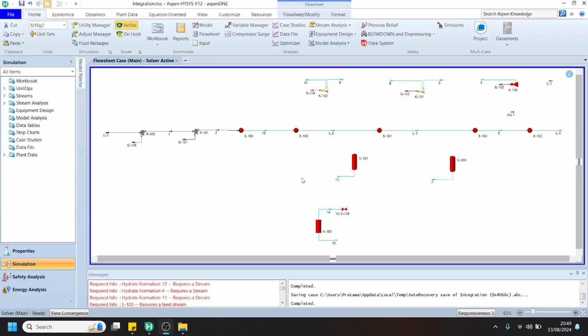You have to provide this component splitter, which represents the molecular sieve, and these two flash tanks in order to separate the water content from the CO2 stream after the CO2 is cooled by natural gas or the cold stream here. You can also provide the component splitter here, which represents the molecular sieve, in order to ensure that there is no water content remaining in our CO2 system, because it can cause plugging or hydrate formation.